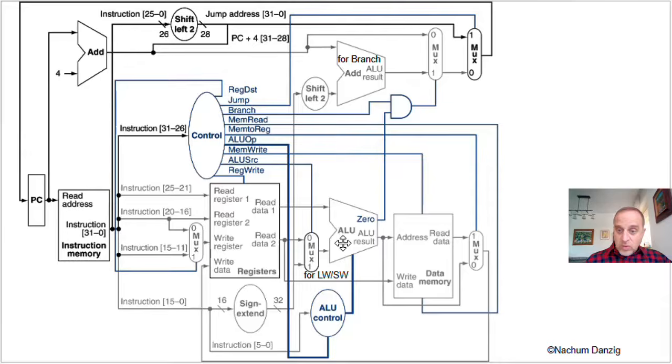Here's the ALU. Here is the data memory, which is our access point to memory for data. That's what we're going to use in a load word command if we want to load data from our array into a register. So we need an access to the data to do that, and that's this data memory unit.